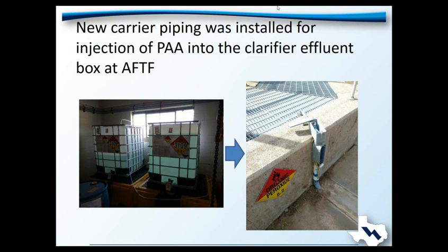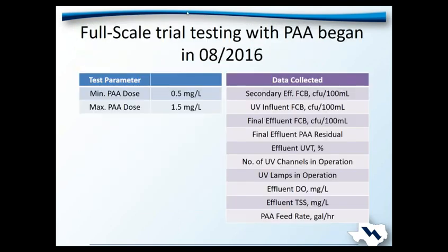You'll notice from this picture that there's not necessarily mechanical mixing. This is a part of the trial and error and the valuable lessons that can be learned from trials like this. There was a discussion early on whether to mechanically mix or to provide some kind of mixing or not. Since it was a trial, we decided, with Little Rock Wastewater, to look at the effects of just going straight from the PTFE tubing into that secondary clarifier effluent collection box, and found that there was quite a bit of success in good chemical dispersion just with that introduction method alone. So we were getting good dissolution of the PAA injected in that secondary clarifier effluent and getting the disinfection we needed. So there hasn't been a retrofit for mechanical mixing in that particular application point.